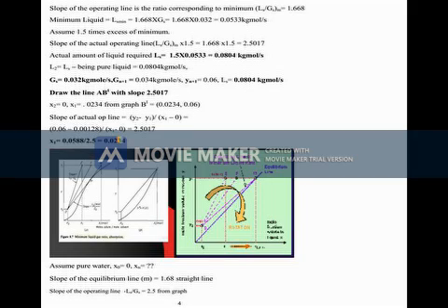Then this height, this space of 40 mm, will be occupied by both froth and liquid. The liquid is a small pocket of liquid, and above that the froth will be. So you have to find out the hold up, and it is to be checked.